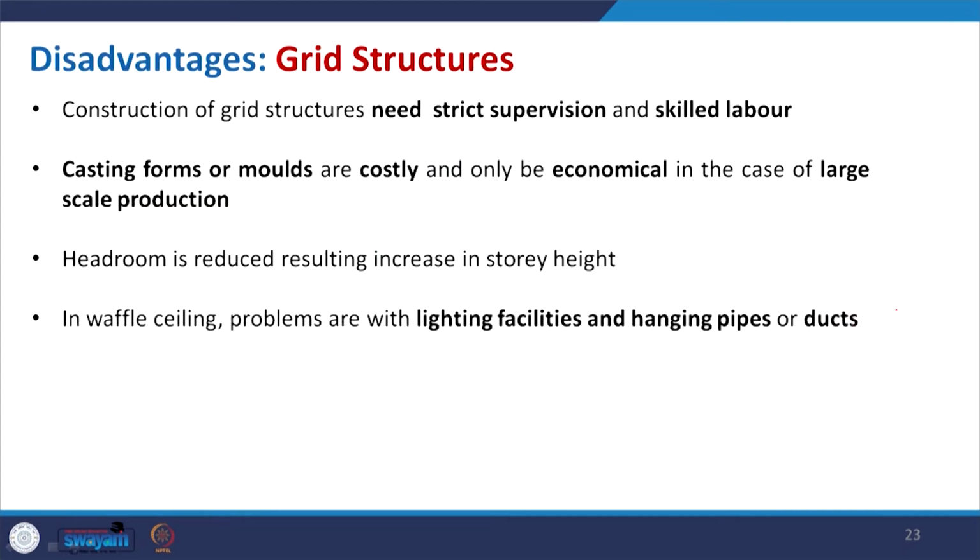Now, coming to the disadvantages: construction of a grid structure needs strict supervision and skilled labor. Definitely proper execution is required, not only in the design but also during the execution, the proper alignment of the reinforcement and the formwork. Especially it is required to be very accurate to get the desired result.